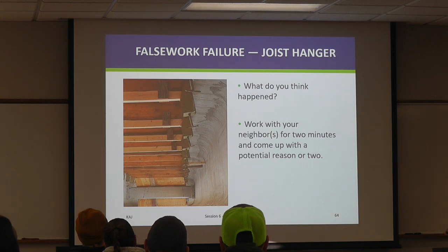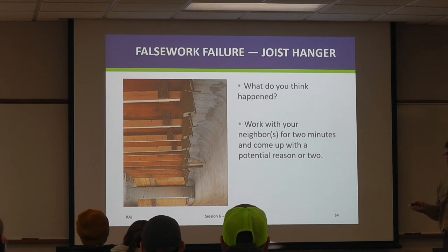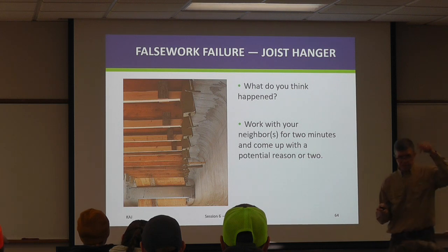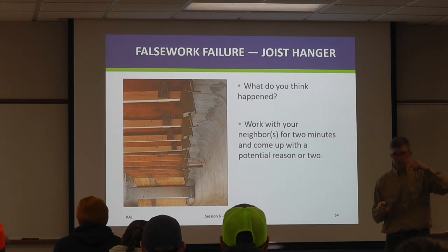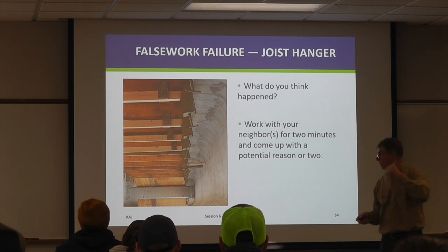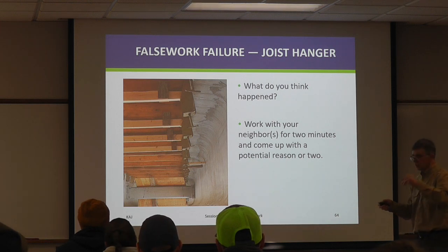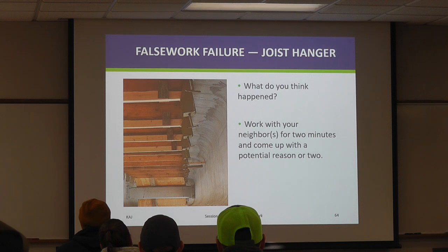So that's one thing. There's another thing that right up where these stringers kind of butt up, there can be a little gap, and if that gap doesn't get filled in with plywood, it gives it a little bit more room to move. Plus, then the deflection of those girders will cause some movement. So those are kind of the things that happen.